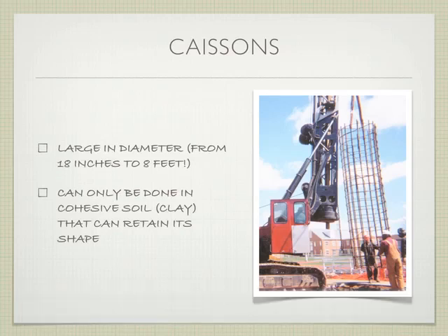The diameter is anywhere from 18 inches, which is relatively small, something you might see on a multifamily building, all the way up to 8+ feet. So they can get very large in size. Obviously, if we're supporting a skyscraper or the Bay Bridge or something like that, much bigger pieces. The thing about it is, because it has to be drilled, it can only be done in cohesive soil. So it can only be done in things like clay, because if we were drilling in, say, sand, when we drill, it fills back in.